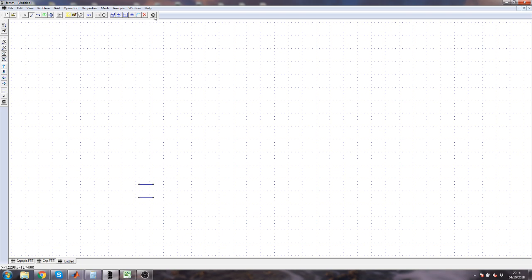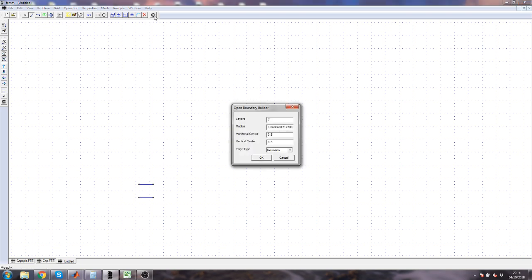As it is, we can go a little bit better than that and use an impedance match layer effectively, where we gently redirect the electric flux rather than force it in a way that's not particularly realistic. So my problem is about a metre in dimensions, so I have a 5 metre radius around that, which is ample. It's really probably a bit too much, but it doesn't matter.